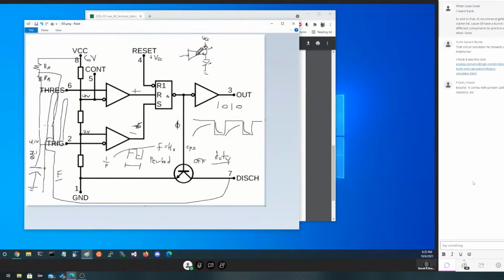So if this has a high value, what's going to happen? Well, if this were high on one side and low on the other, we would think this could turn on. But we said high and high. If they're both high, that means there's not enough value difference between the top of this inverter and VCC to give it, in this case for an LED, a 2.1 drop.